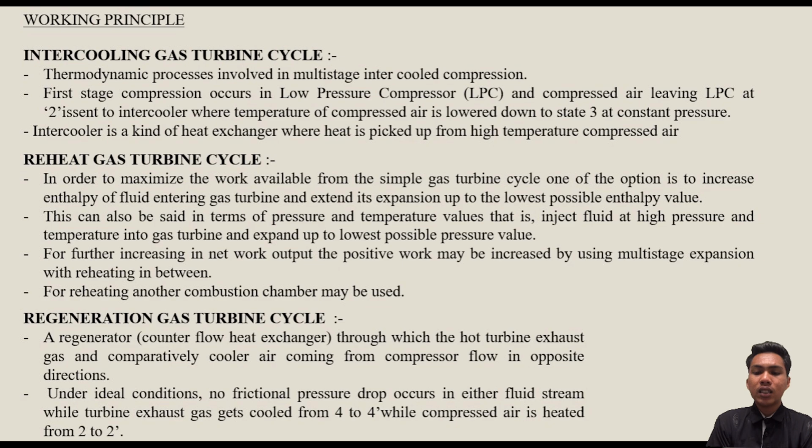Under ideal conditions, no frictional pressure drop occurs in either fluid stream, while the turbine exhaust gas gets cooled from state 4 to state 4 prime, while the compressed air is heated from state 2 to state X. That's all from me for the working principle.